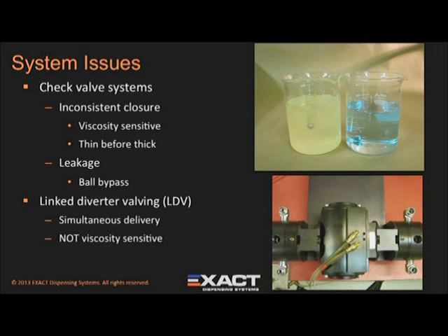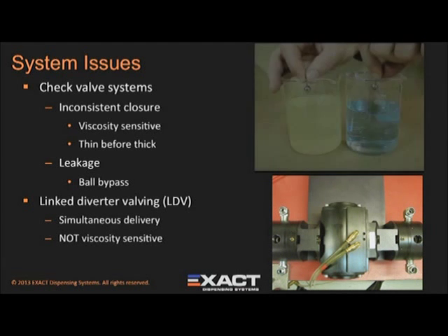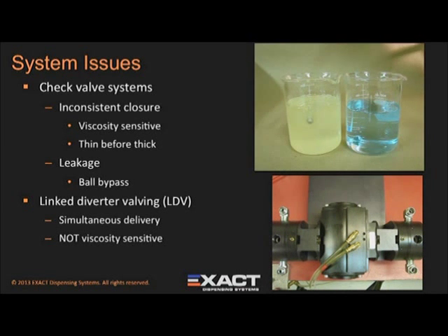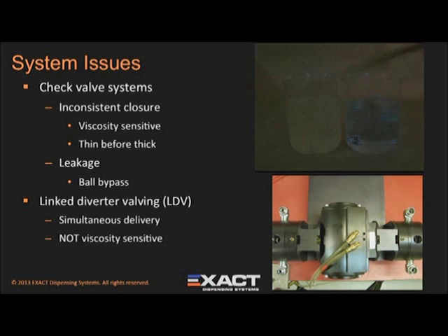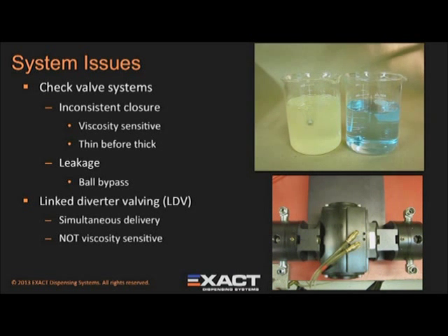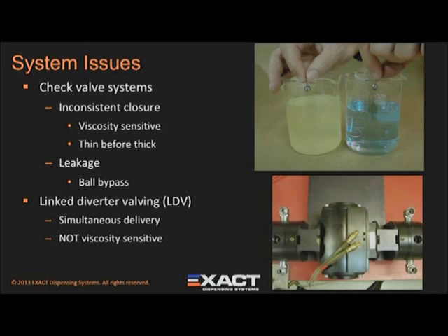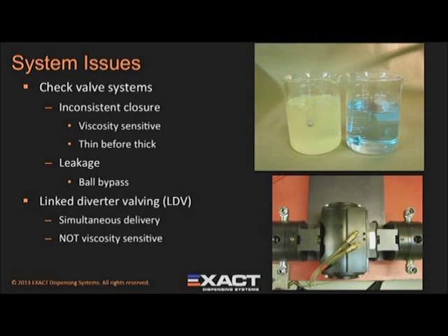There are many systems on the market that depend on, quote, check valves to control the meter mix function. As you can see from the video, the closing of check valves is highly impacted by the viscosity of the fluid. The thin valve always closes before the thick valve. At Exact, you can see in the video, we use what is referred to as an LDV, linked diverter valve. This assures simultaneous valving of the A and B components and is not viscosity sensitive.